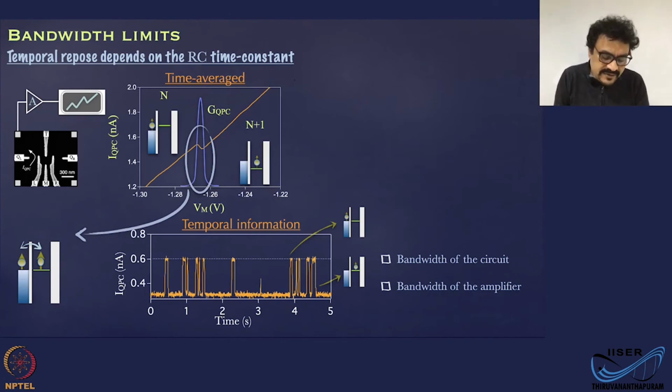So generally what you have is a quantum dot device, and when you are measuring the current to the sensor, that is the channel, you will get a bump-like structure, or peaks in the conductance, as a function of one of the gate voltages, and that is going to tell you when the charge transfer is going to happen.